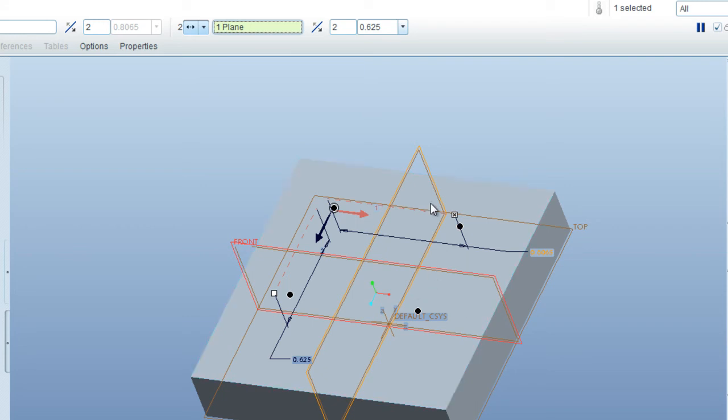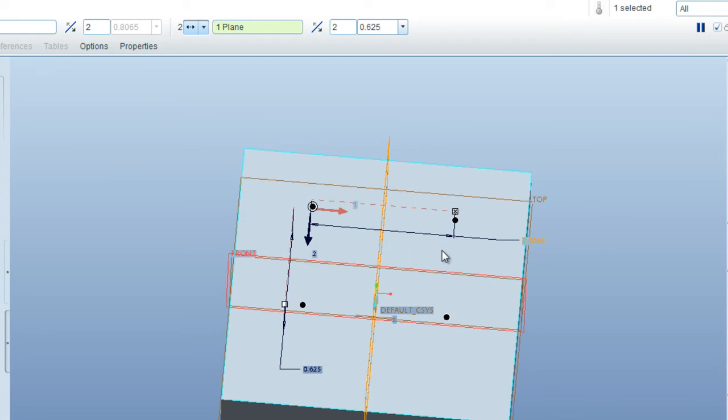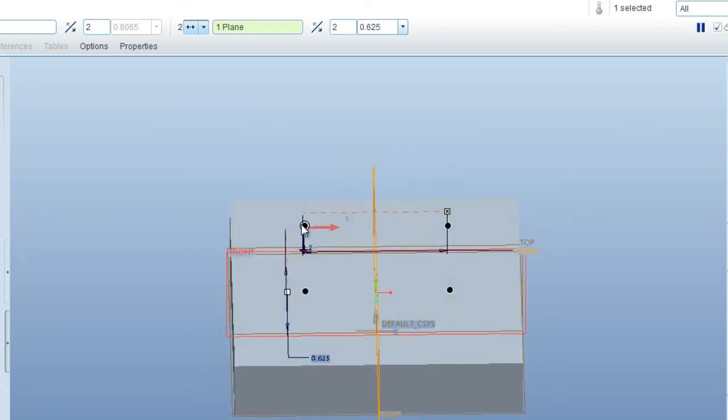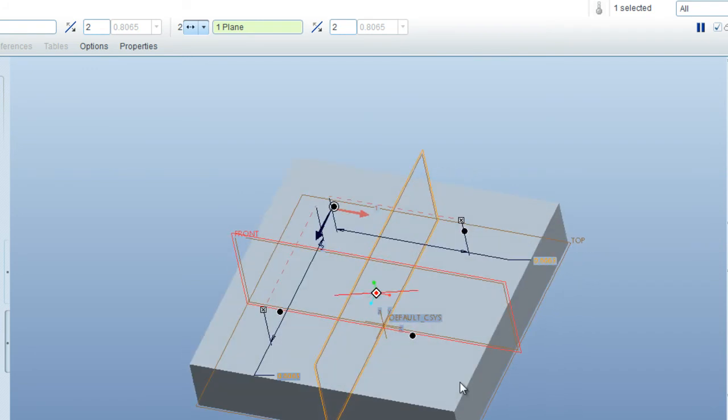So now you'll see that in our row length direction our checkbox is X'd out, meaning that we can't modify that because it's relation driven. But you'll see that our length now appears to be 1 Lego unit, which it is. We'll do the same here. Say LU, enter, enter. So now we have our pattern set up.